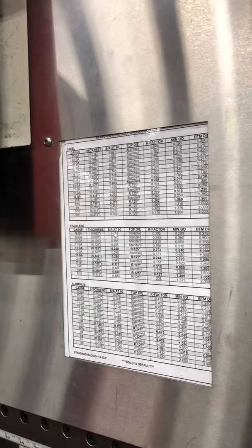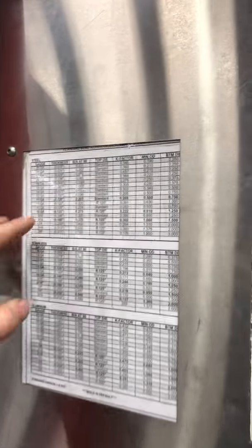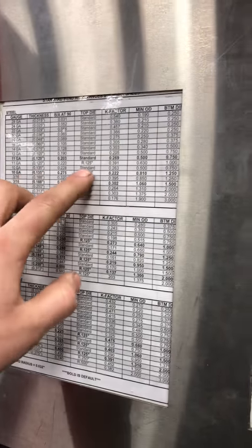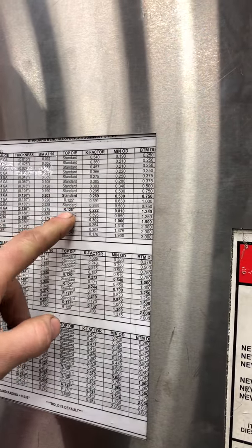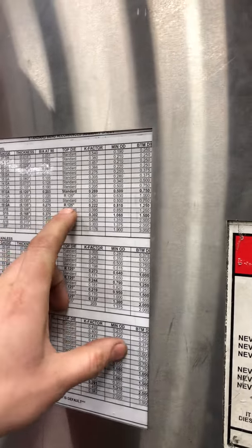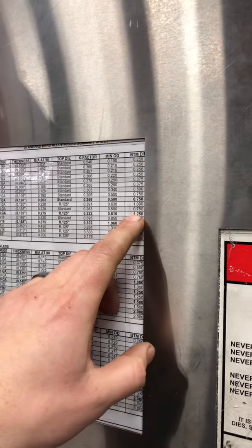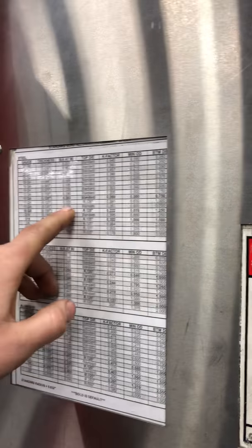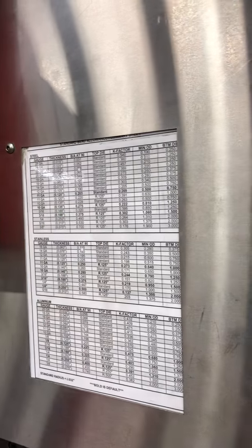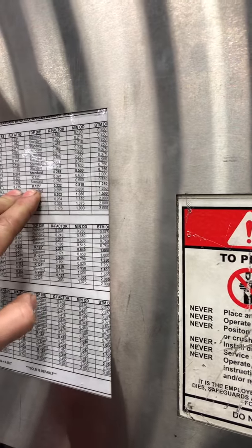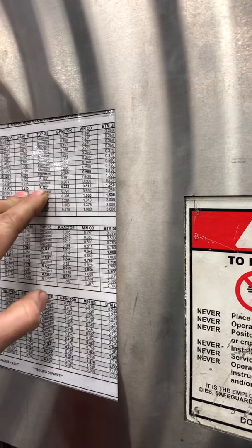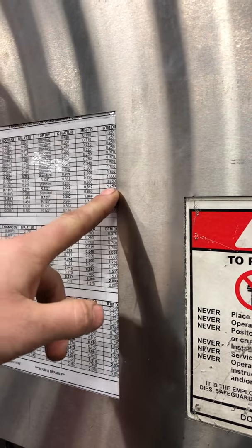So it's going to tell the operator, I'm going to stretch, let's say for 135, he's got 2 choices. So your inside radius, are we using an 0.32 radius, or are we using a 1/8 radius, right? And then they can follow that down and determine what the bottom die size is, right? But how much it's going to stretch. So we can use that information and we can put that in here. So 135, they're looking for, say if we went with this one, 275 is how much it's going to stretch, right? They want a 1/8 radius and a 1 1/4 bottom.